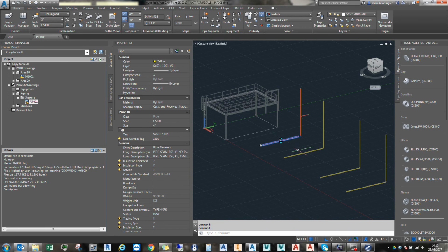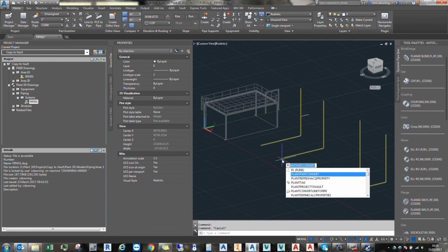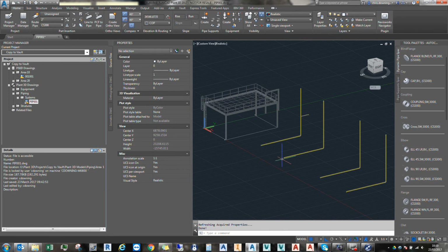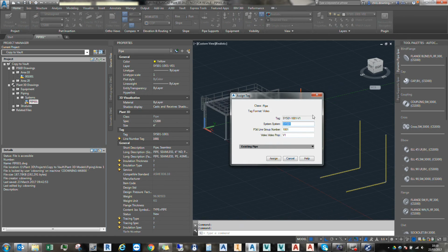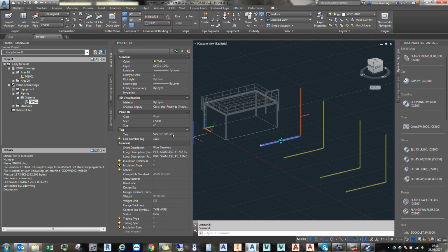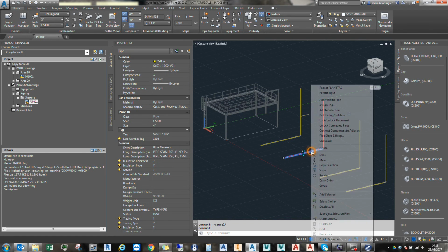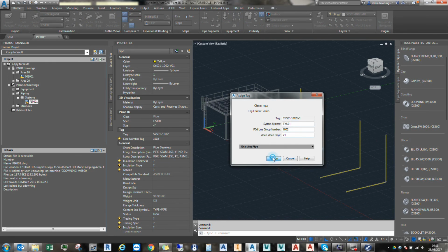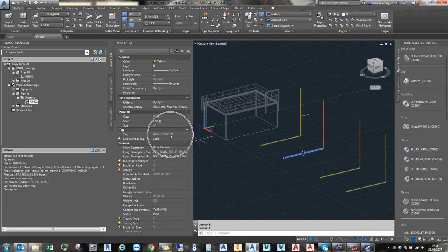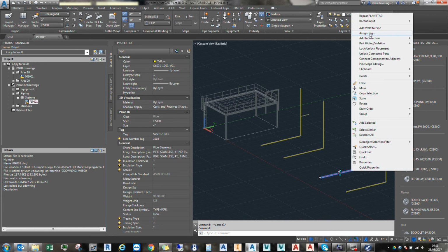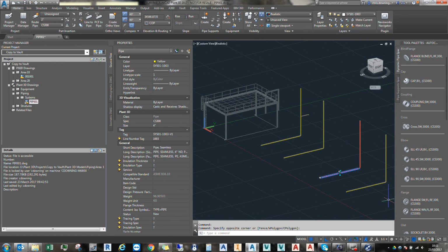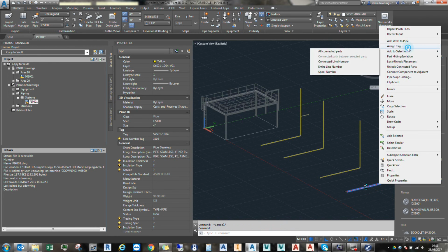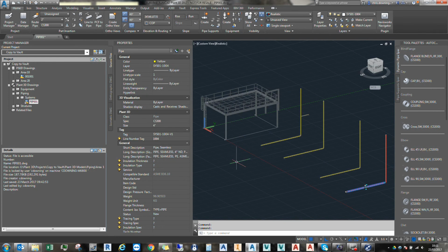So what we should see now is if I do a plant refresh properties, drawing's fine again, we can see down here they should be all updated, and we can see now the tag is now picking up the V1 as well. Okay, in some cases we have to assign it just to make sure, so it's good to get your tag format set up prior to making these drawings, so you don't have to go through each pipe, now that's working there, and reassigning it. So make sure you get this tag format correct before you model your plant, because you don't want to have to go around doing what I'm doing here for these 4 pipes on 100 plus pipes. Okay, so make sure you get your format correct first.